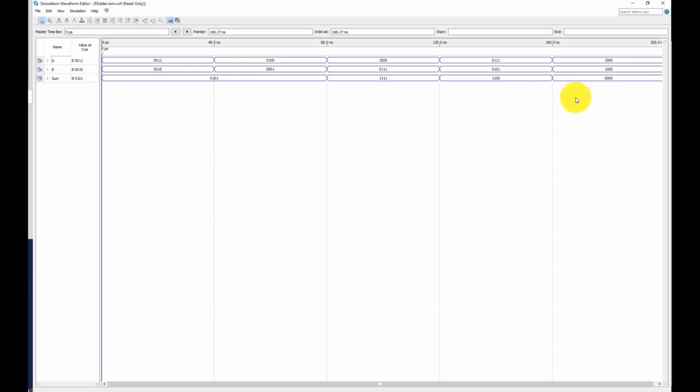Okay, when we do the addition on paper, we have unlimited space to do so. But when it comes to computers, just remember that the number of your full adders will determine the number of bits that you can produce as the output. Okay, guys, so this is called an overflow, and this is what I'm going to explain shortly.